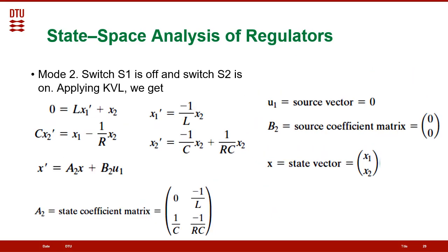So now we find the equation for the converter during the off state. In the off state, the only difference, as you can see, is that the voltage source does not exist because the switch is off. So we do the same thing, and we have these two equations. Then we can recall the new state in the off state by writing 2.